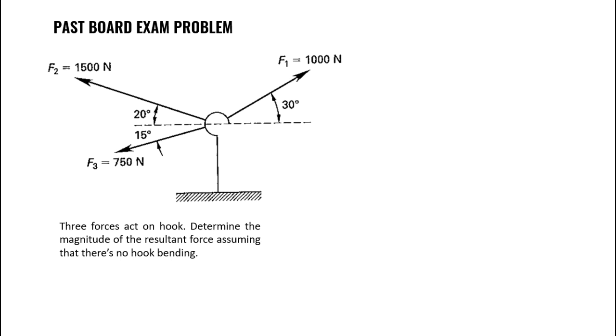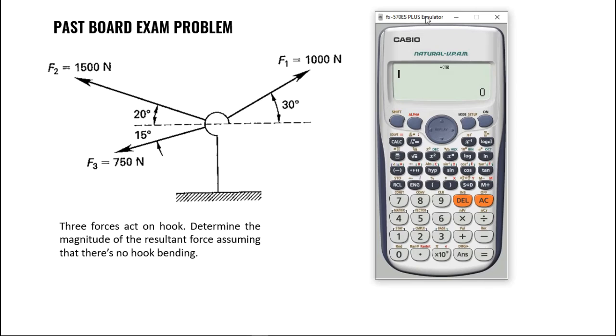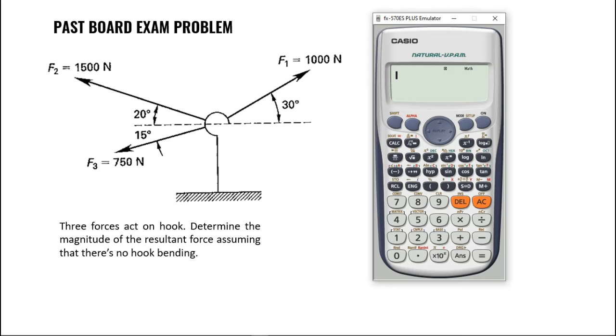So open natin guys yung calculator natin. Now of course, ang first step natin pag calculator technique guys is i-shift clear natin. Shift 9. Naka-clear na siya. So 3. So shift clear para malinis yung ating calculator. Then for systems of forces, you can use your mode complex guys. So mode complex tayo. So this is 2. Then, input natin lahat ng forces. So, 1,000. So, input natin guys yung angles. Yung angle natin is with respect to your positive x-axis here. So, ito yung reference line natin of the angle.